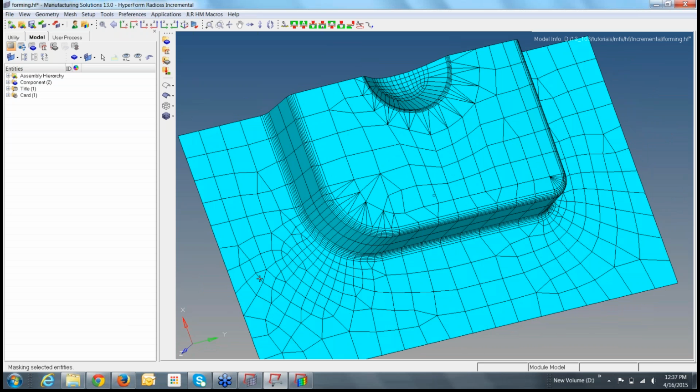Here we have generated this extra region such that the binder is created based upon it to hold the blank. So when you are generating a CAD geometry in your CAD environment, be it any software, make sure you generate it with an extra flat region, or even a slightly curved region based upon your component, such that you use it to generate the binder.